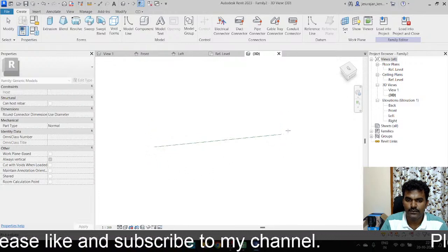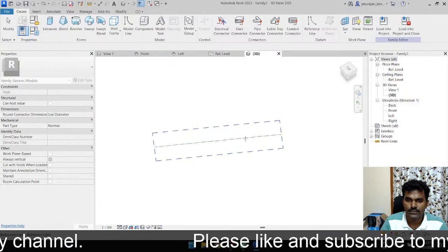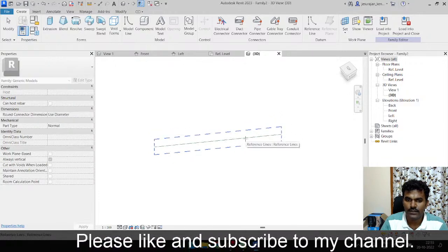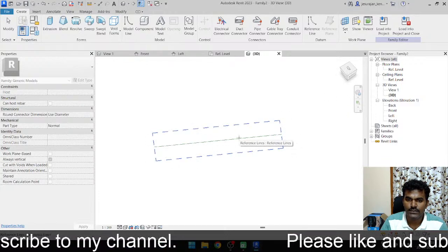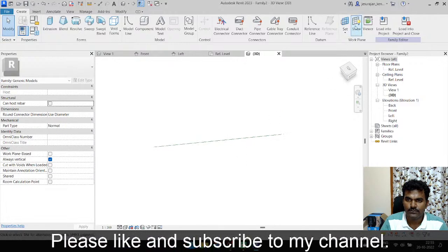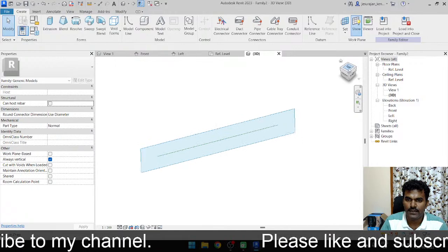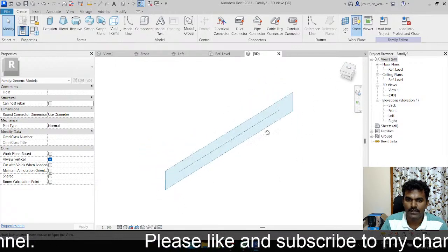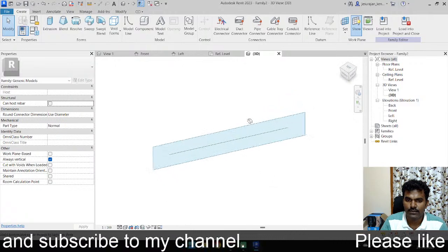You can see 1, 2, and in here you can see 2 more. Totally 4 reference planes you can get. So you have to be very careful on which reference plane you are selecting. I'm selecting this one. If I don't understand, I can enable show work plane and check which plane I'm making the work plane. So this is what I'm making the work plane.